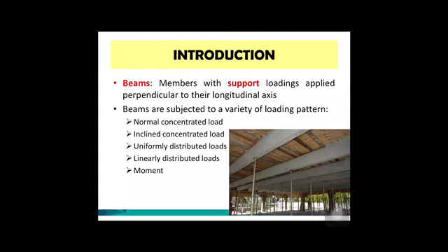As for the introduction, a beam is a member with supports, with loadings applied perpendicular to the longitudinal axis. Beams are subjected to a variety of loading patterns such as normal concentrated load, inclined concentrated load, uniformly distributed loads, linear distributed loads, and also applied moment.